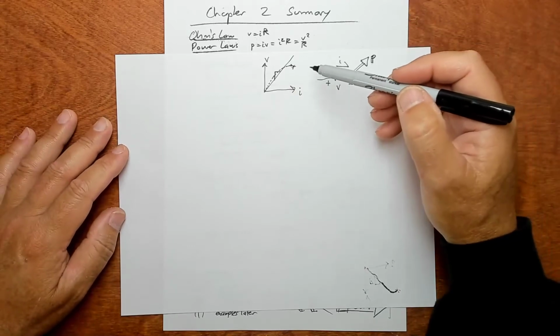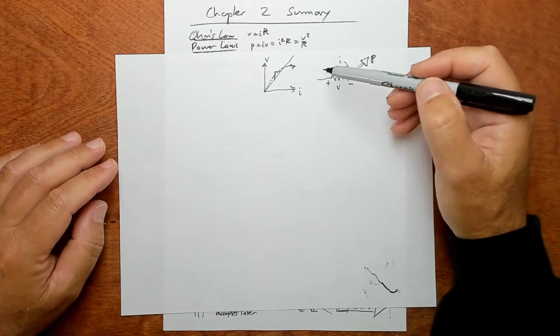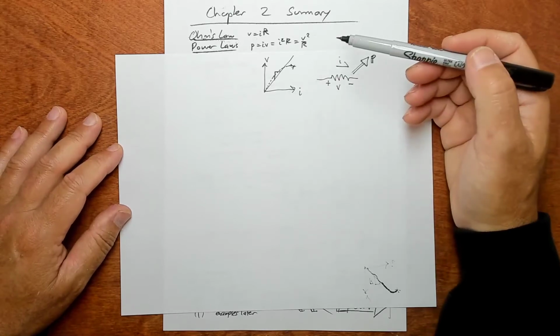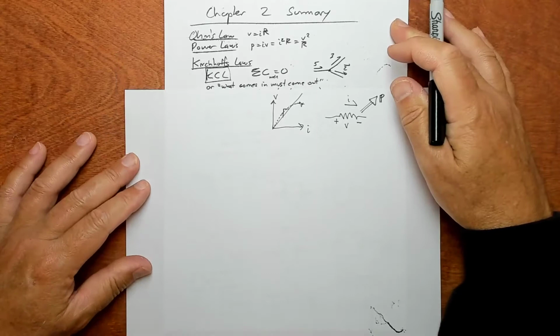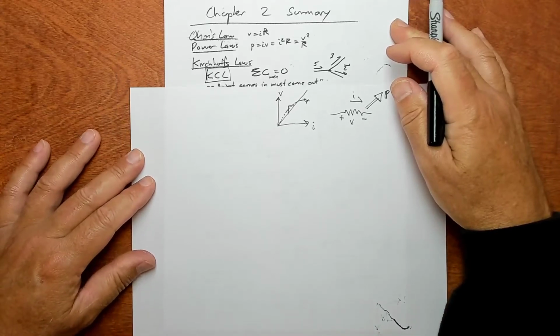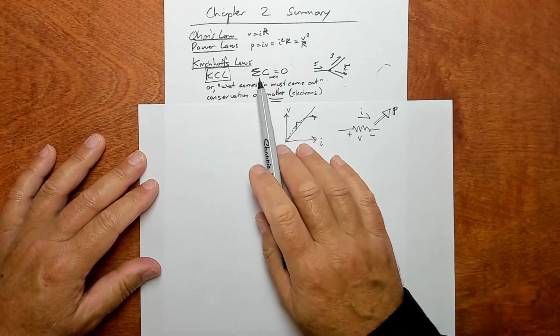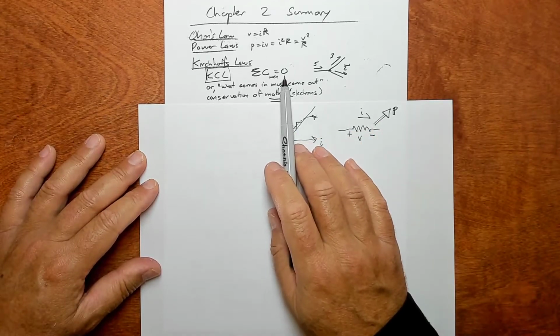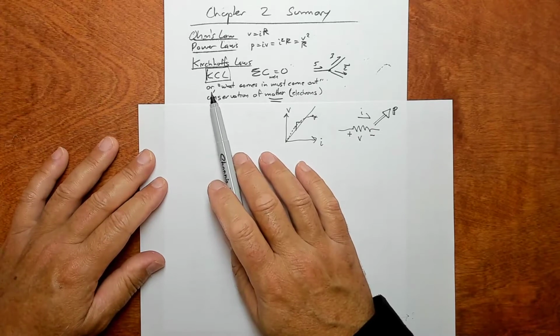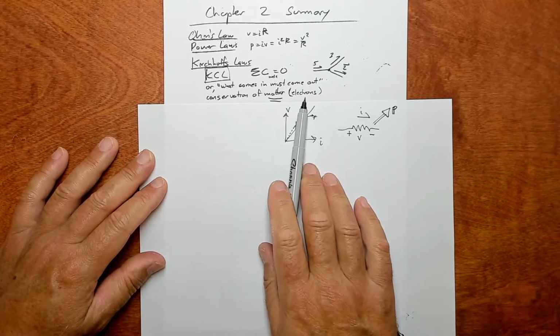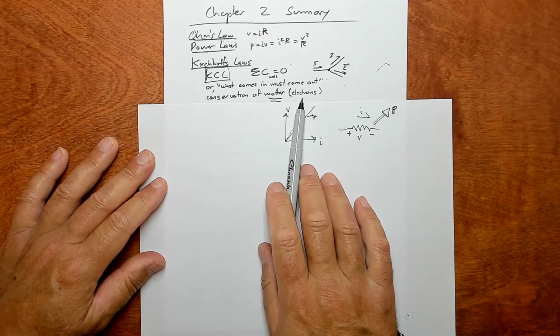Like I mentioned in a previous video, if you don't consider the real world simplifications of your model, you're not doing engineering. You're just doing math. Okay. Then we've got KCL, or Kirchhoff's current law. This just says the sum of the currents at a node is equal to 0. Or I like to think about it like this: what comes in must come out. It's kind of conservation of matter, because electrons are matter. You can weigh them. They have a tiny, tiny weight, but they are mass.